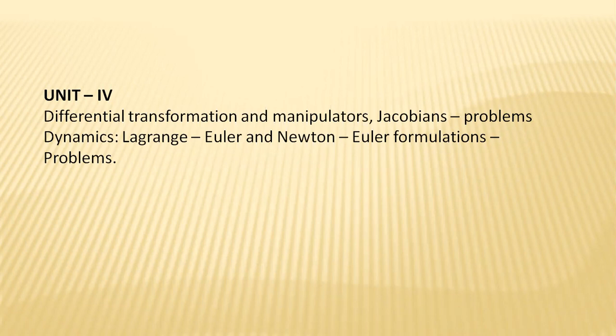So at this moment, after the entire transformations have been considered, nothing but rotation of link 1 and one more rotation of link 2 and one prismatic movement by link 3, within the work volume, that is the work envelope, in its stretching or expanding mode, the end effector is surrounded by the links connected to it, and the space occupied in the working zone by this end effector is nothing but the work envelope.